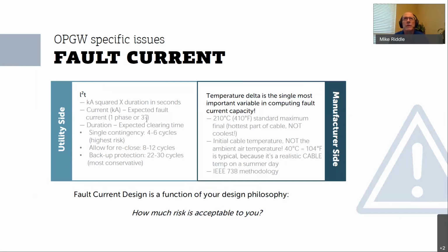Faults aren't really common, but they do happen. When they happen, there's a lot more single phase faults than there are three phase faults, but again, they do happen. Now, you can make an economic case that maybe worrying about a single phase fault condition is good enough 99% of the time. The difference between the two is not a factor of three, as you might originally think.